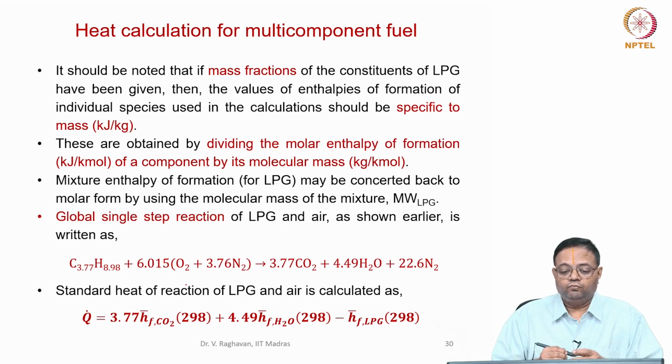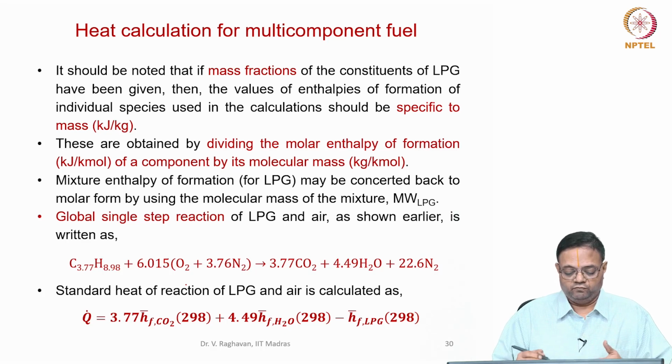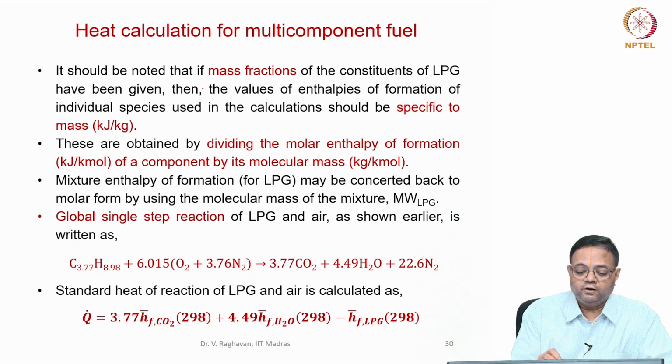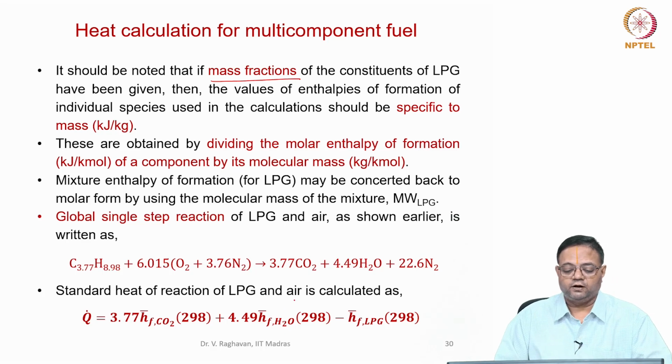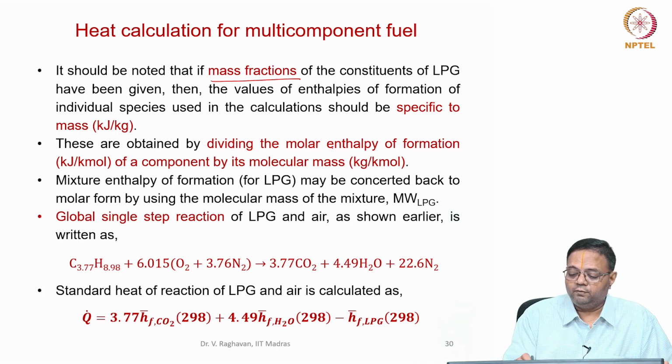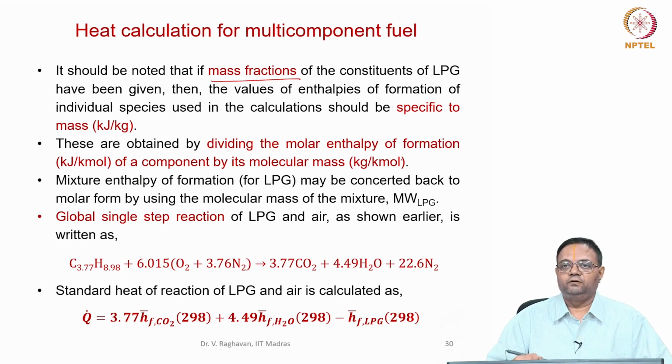Okay, now before going to the equation, I want to mention one point here. If mass fractions are given, then we have to use the mass-based specific properties and use the mixing rule which I have demonstrated before. In order to do that, you have to divide the molar enthalpy of formation of a component by its molecular mass to get the per kg specific quantity. So now the mixture enthalpy of formation for the LPG is got.